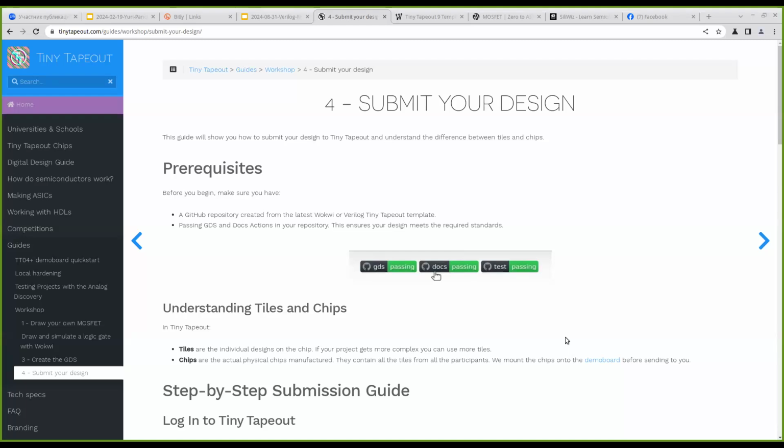But his infrastructure is actually very convenient for training engineers as well, because he has complete OpenLane underneath, and you can see static timing analysis reports and produce GDS files. So this is very efficient for our examples. He also allowed coding in SystemVerilog. So let me show you my own design with his infrastructure.